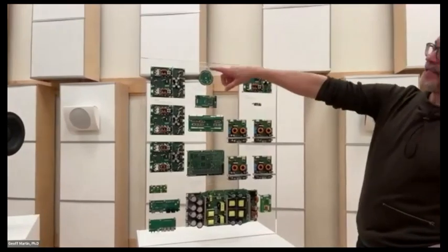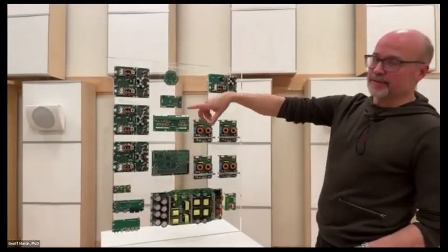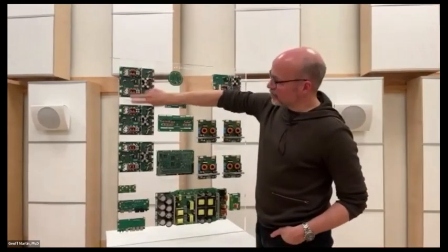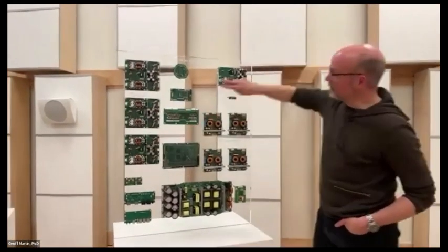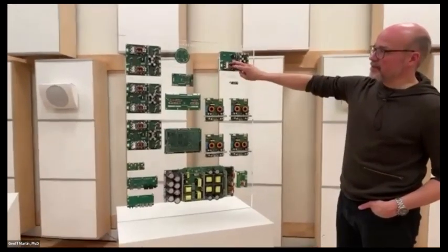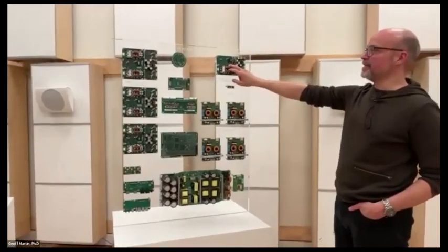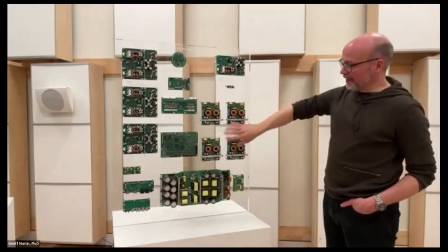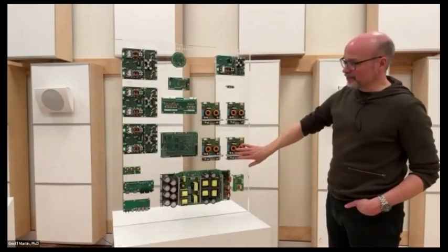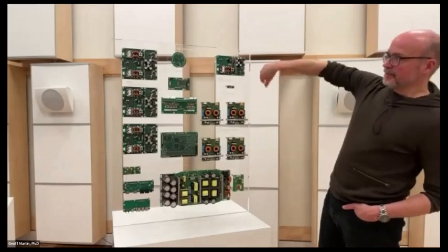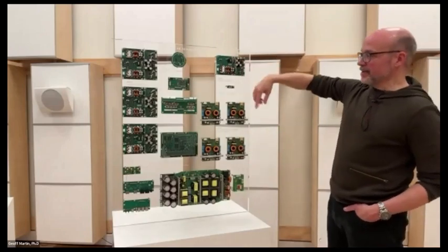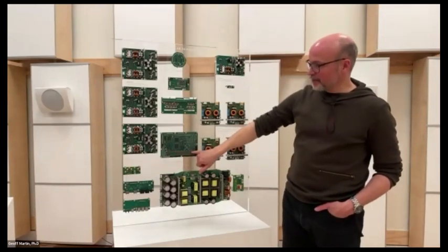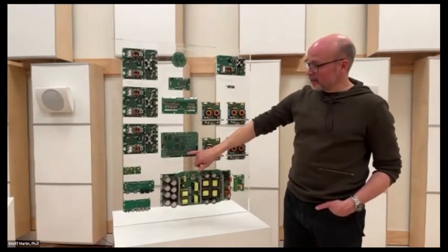So we knew that we had 7 tweeters, 7 mid-ranges, and 4 woofers. As a result, we needed 2, 4, 6, 8, 10, 12, 14 smaller amplifiers. These are 300 watts each from Ice Power for the mid-ranges and tweeters, and then 4 1,000-watt amplifiers for the 4 woofers. And those 14 plus 4, 18 channels are driven by 18 DAC outputs on the DSP board, which are fed